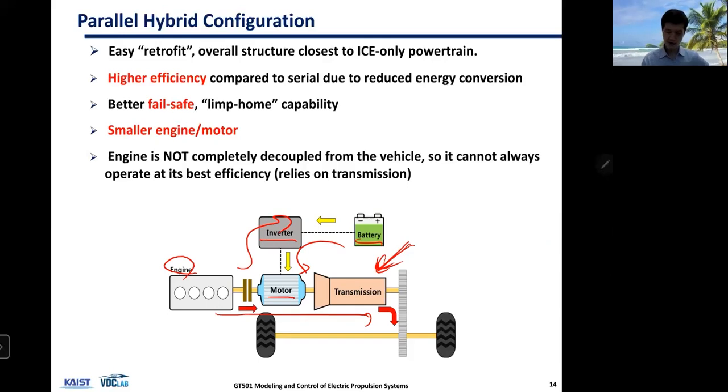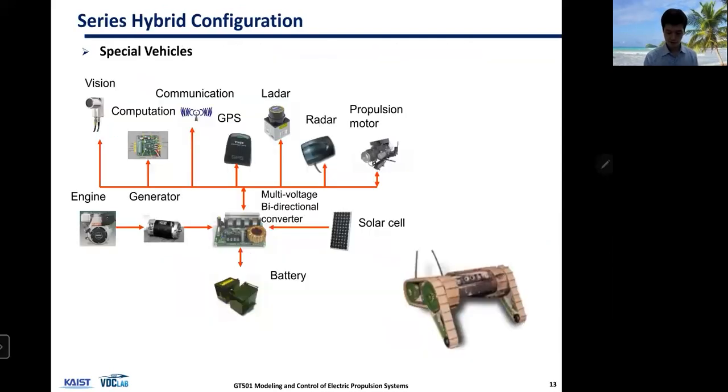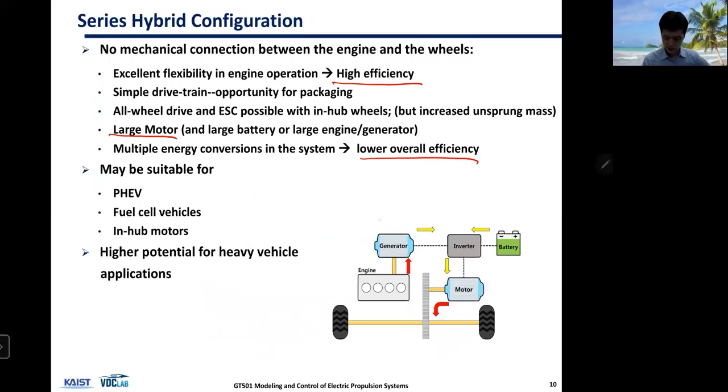But because it's mechanically connected, the power transmission doesn't require the energy conversion losses where motor and generator usually suffer. So if your generator has 90% efficiency and motor has 90% efficiency, then even if the inverter is 100% efficient, by the time you get to the wheel, you only have 81% and 20% is lost.